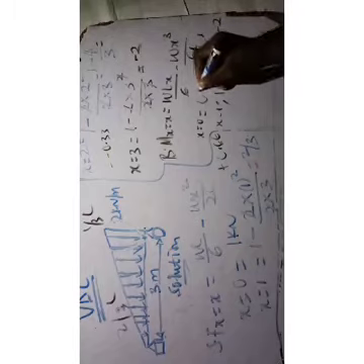So when X equals 1, using the formula, your answer will be 1 times 1 already, and that is 1 minus WX cube over 6L. W is 2, that will be 2 times X cube. Considering 3 is the total length, when X is 3, that is 2 times 27 over 6 times 3, that is 18, and that will be minus 2 kilonewton meter.